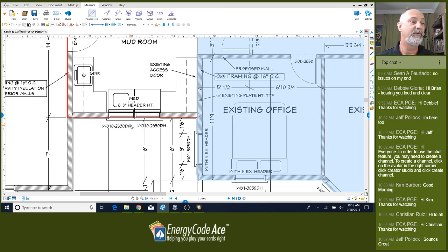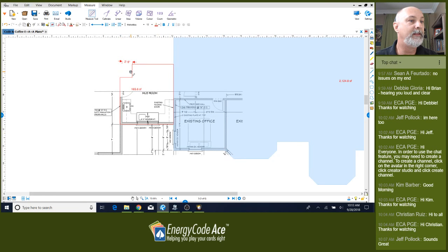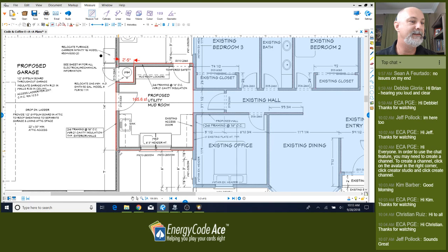Or if you prefer, you can just lump all the similar windows in the same orientation together in one big area. That's fine. In this case, I'm going to combine those 2 windows as a new 5030, so 15 square feet of window there. My left wall is a demising wall. I don't have a left exterior wall. I'm going to handle that as an interior wall later.